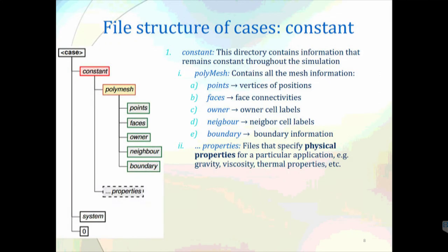Now, moving on, I will remind you of what we discussed last time about the file structure. I will not go into details, but in OpenFOAM we had the case directory, which for our case was cavity. Remember, we defined a new directory in Windows, and we named it cavity. Inside cavity, there were 3 different types of folders: one named constant, another named system, and the last one named 0.